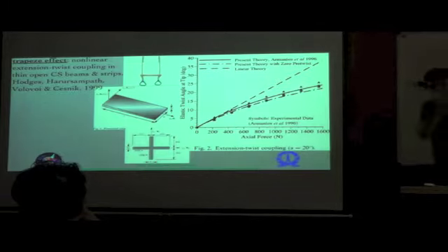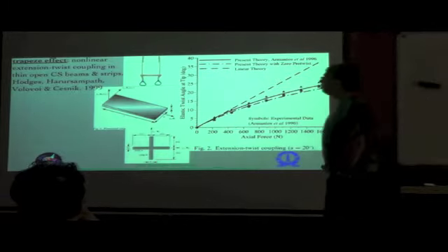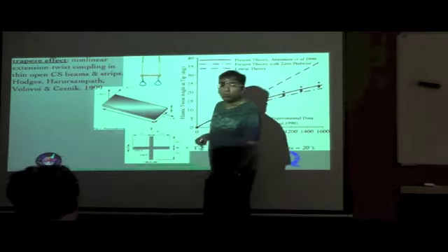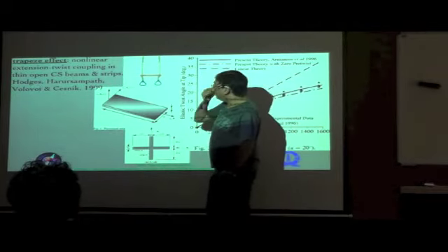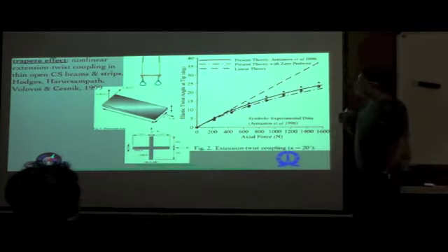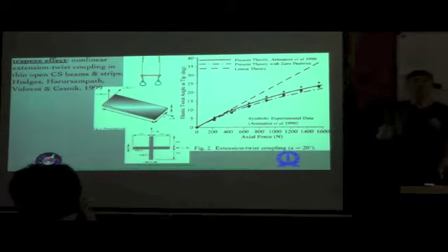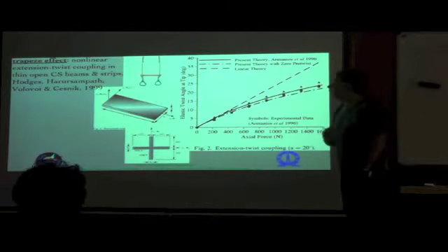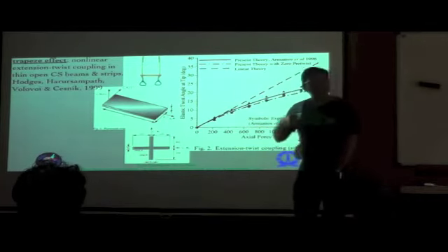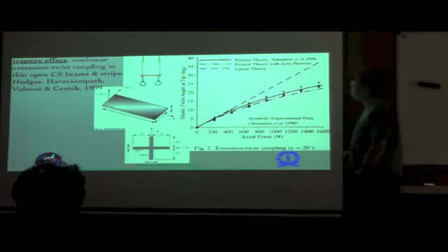Okay, next let's go through a similar analysis for the trapeze effect. So this is the trapeze apparatus that I was talking about, and here as I said, it's nonlinear extension-twist coupling, and this is something which is very common in thin open cross-section beams and also strips. By which we mean thin rectangular cross sections and thin airfoil cross sections, for example.